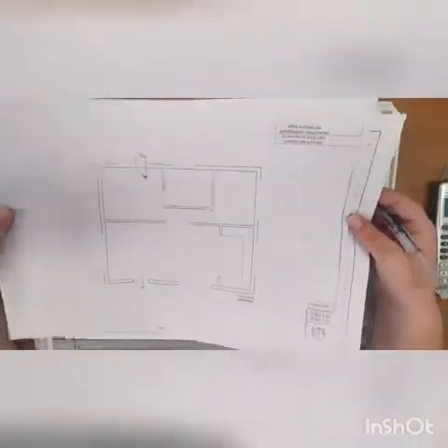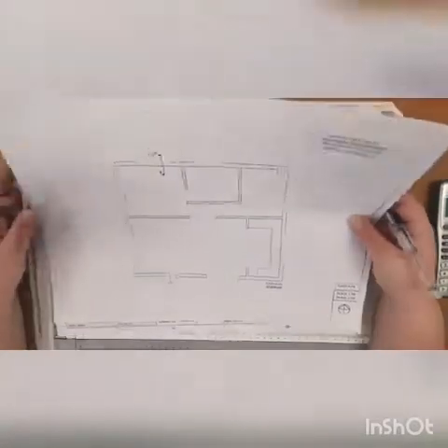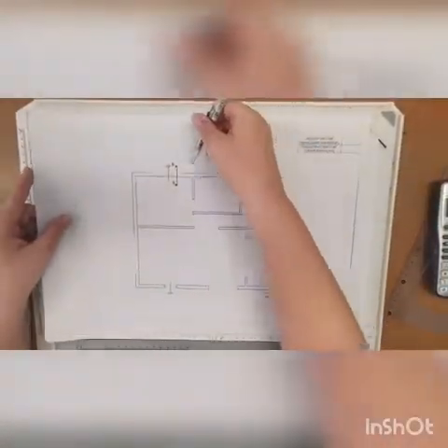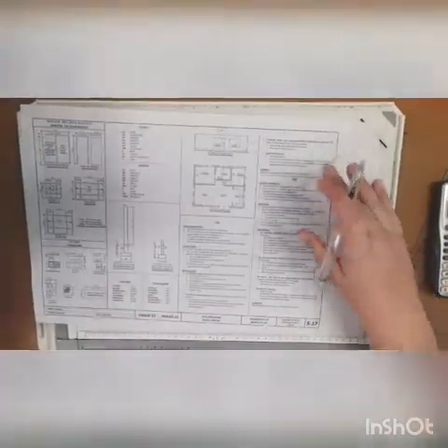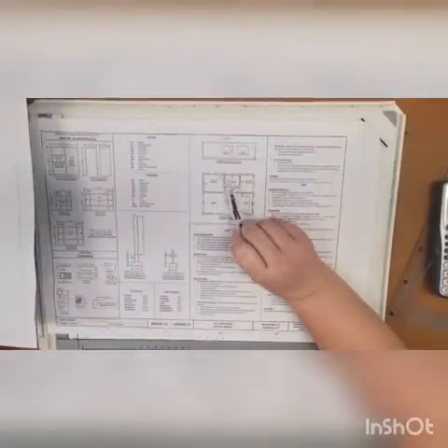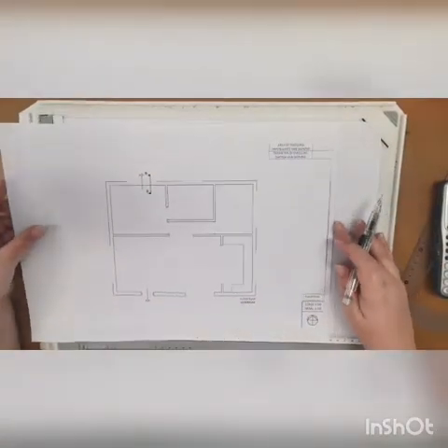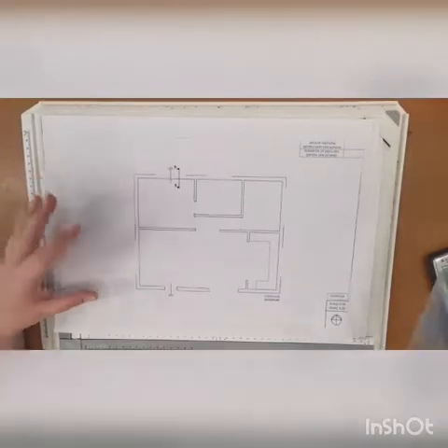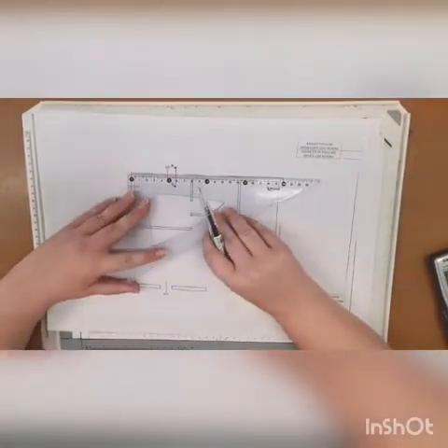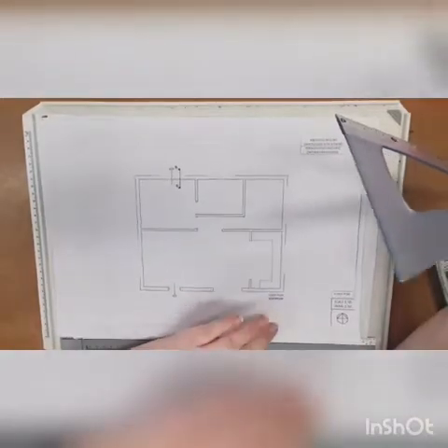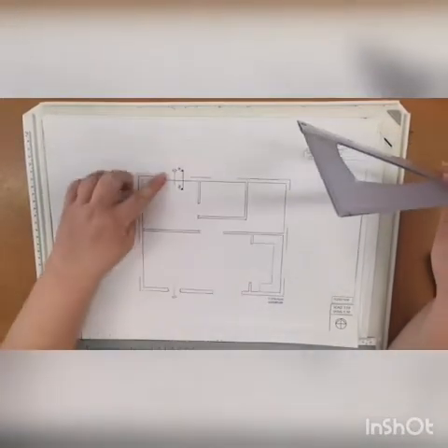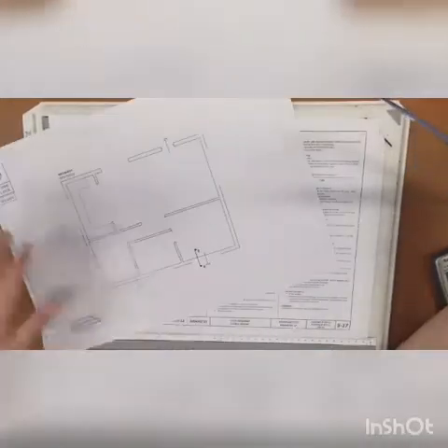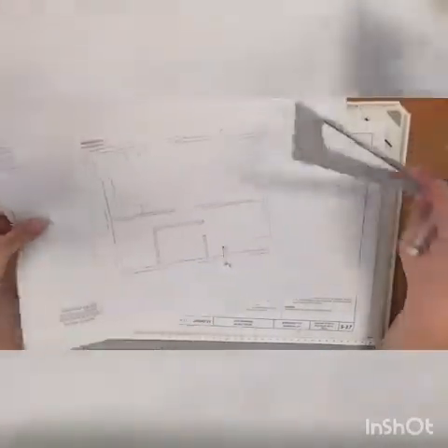So I'm going to do a north elevation to start, north being this one. If we look at the incomplete floor plan, I see I'm going to have 2 windows. Now I'm doing the elevation at scale 1:50, which is exactly what the floor plan is. Therefore I can use exact measurements from here. Remember, when we are drawing an elevation, if I'm doing the north one, I don't look at it this way. I turn it and I look at it this way, as if I was standing outside looking at it. So let's start.